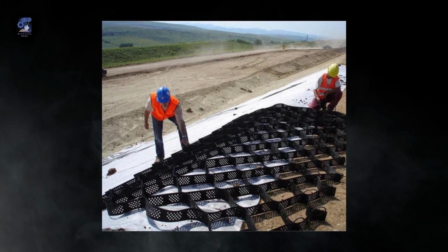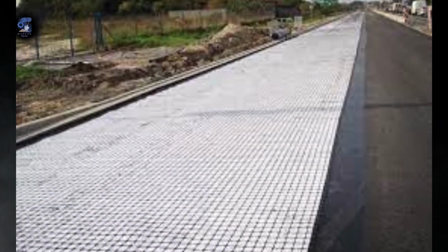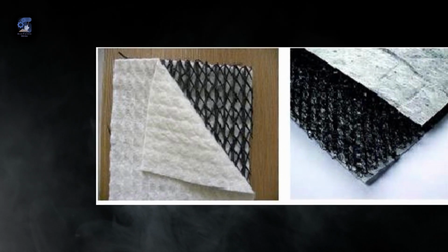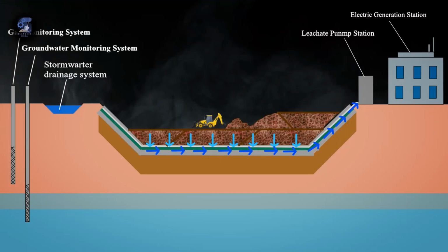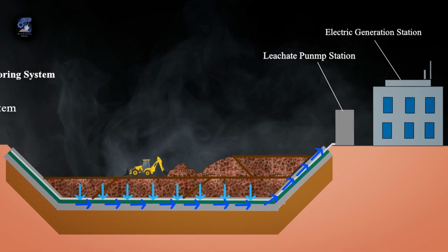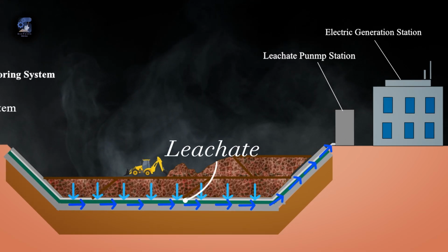As I discussed earlier, one of the critical elements in landfill operation and management is the control and removal of leachate. A geocomposite layer used to create drainage systems for various applications such as in highway pavements, foundations, or tunnels is the first element in the primary liner in landfills. It consists of a plastic net core that is sandwiched between two geotextiles or between a geotextile and a geomembrane. The geotextile provides a filter function, allowing water or gas to pass into the net core while preventing soil particles from clogging it. The core collects and transports the leachate to a collection point.